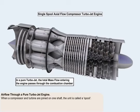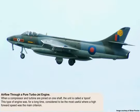When a compressor and turbine are joined on one shaft, the unit is called a spool. This diagram shows a single-spool axial flow compressor turbojet engine. This type of engine was for a long time considered to be the most useful where an engine with a small frontal area was required, such as in fighter aircraft, where a high forward speed was the main criterion.